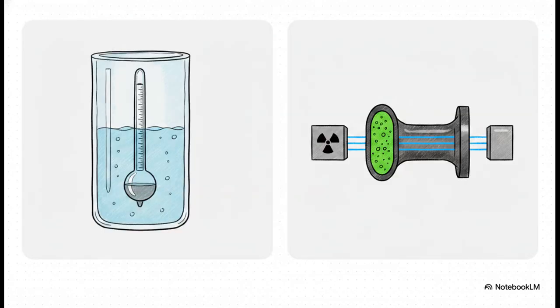But hey, what happens when things get dangerous? Let's say we need to measure the density of a violently corrosive acid. Dropping a standard hydrometer in there? Yeah, that would just leave you with a melted piece of really expensive plastic. Instead, the plant sees the density using a safe external radioactive density analyzer. It just shoots a tiny amount of radiation straight through the thick metal pipe and measures how much is absorbed by the fluid inside. Boom!